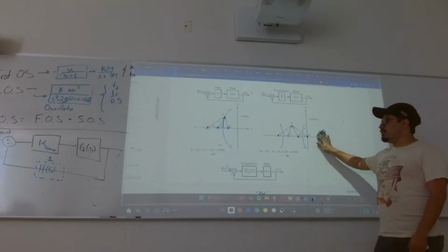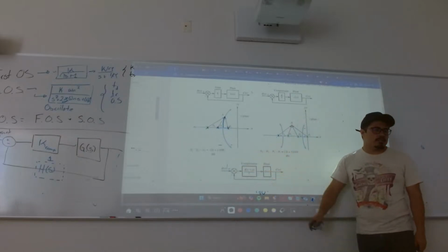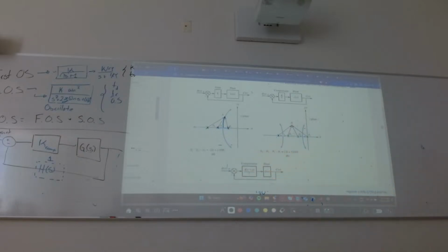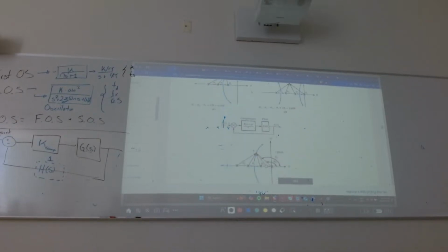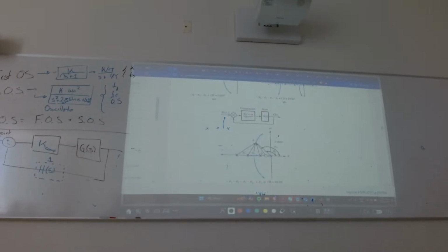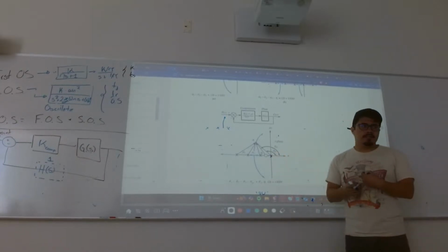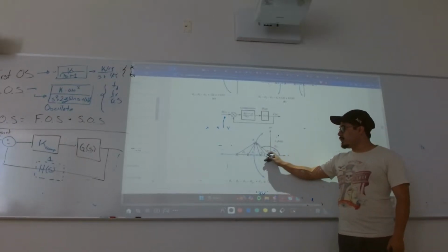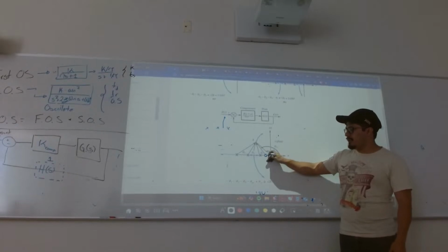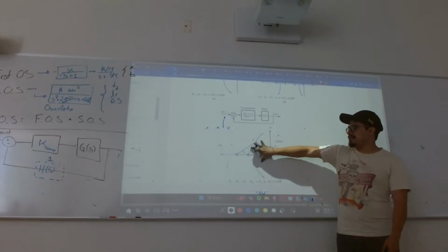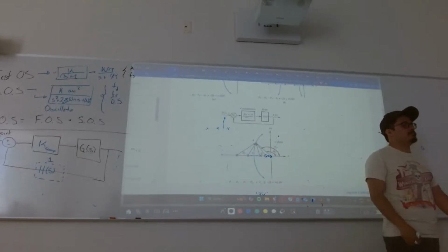Okay, so he says let's introduce a compensation. The compensator in the shape of k times a zero over an integral, right? Which, as we saw, is the general shape of a PI controller. So he says, okay, look, I'm going to introduce the zero you wanted, and a pole really close to it, so when it gets attracted, then these guys behave kind of the same.